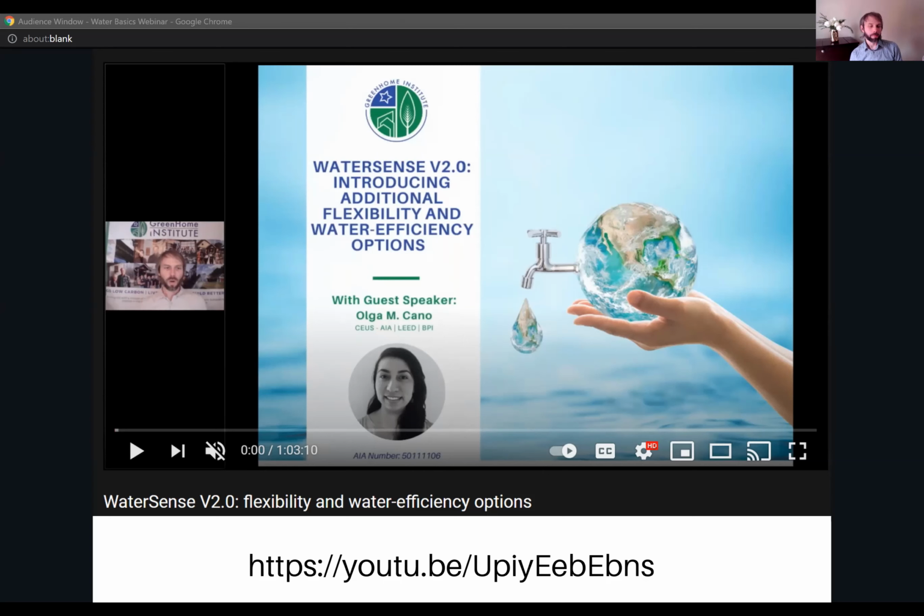So like I said, going back to the shower example we used, if you've got clients who love high flow showers, well, let's say, okay, let's find ways to save water somewhere else. Let's reduce water in the toilet, the aerators, the landscape outside. We'll find a way to save water, much in the same way, if you've got someone who's got really thick insulation, but they don't have great windows, well, you can just improve your insulation, your air sealing. It's the same as an energy model.